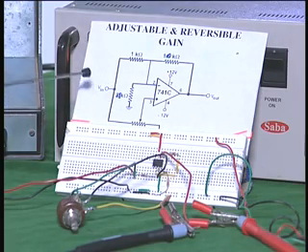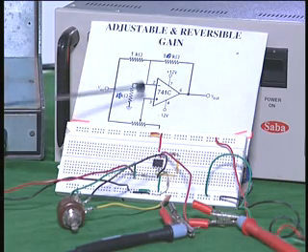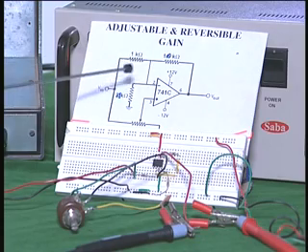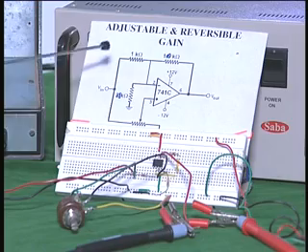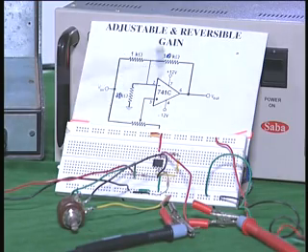When the input voltage is very low, then you should increase the gain, and when the voltage becomes larger at the input you should reduce the gain. So in several applications you would find the variable gain amplifier very useful, and you can make use of this configuration for achieving such a variable gain amplifier. Now we have seen the adjustable and reversible gain amplifier. The demonstration we have seen, the theory also we discussed.